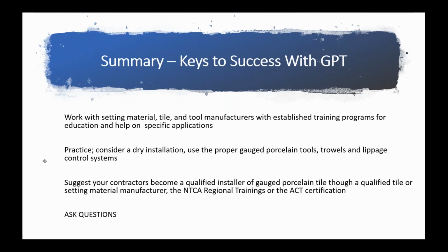Sometimes, depending on the installation, it makes a lot of sense to try and do a dry installation. When you're dealing with tiles that large, it takes a variety of different people to put up one panel. You want to make sure everybody understands their role and how that tile is going to go to the wall. As an example, typically you'll hover it right before the wall and then kind of push